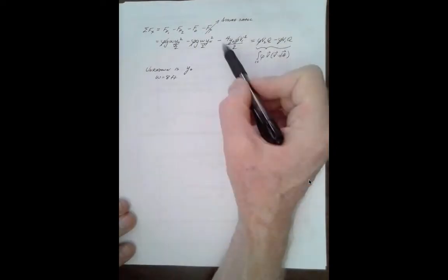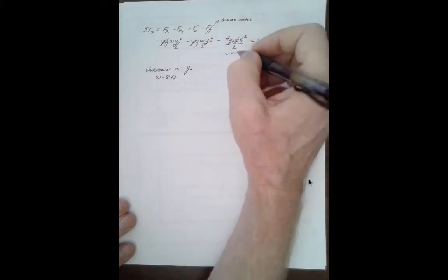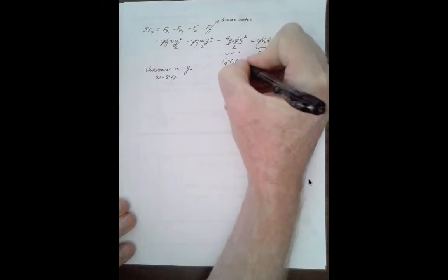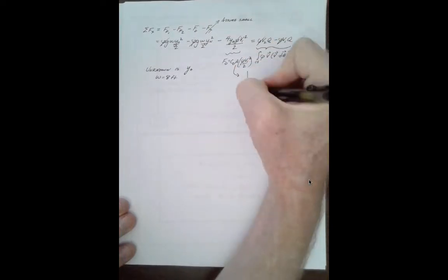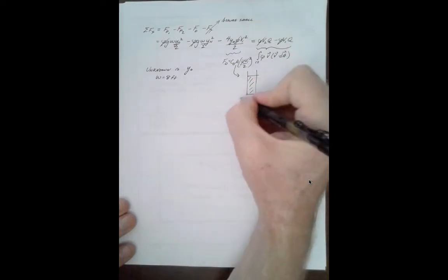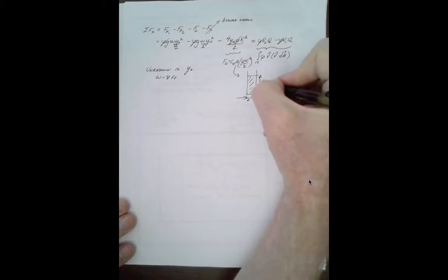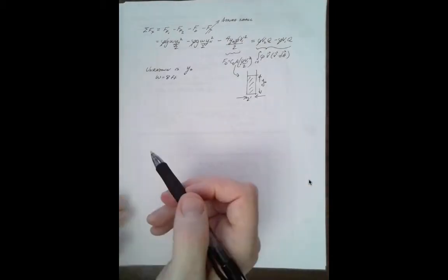The 4 about here in the projected area, the drag force, as you recall, is C sub d times the area, rho v1 squared over 2. The area is the area of the pylon. So that's the 2 feet times the y0. So that's where that's coming from.